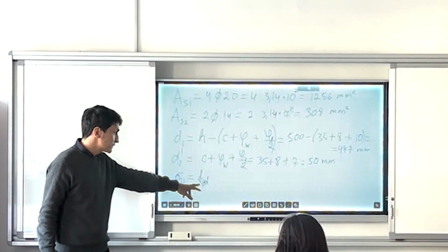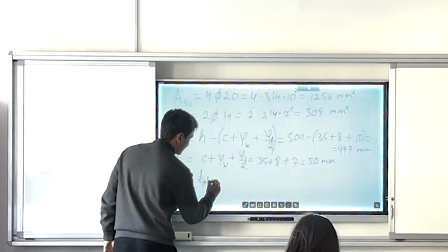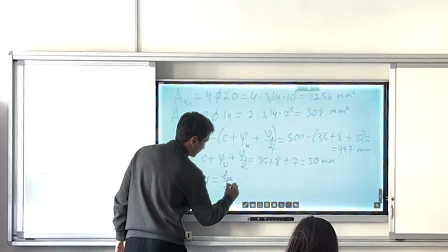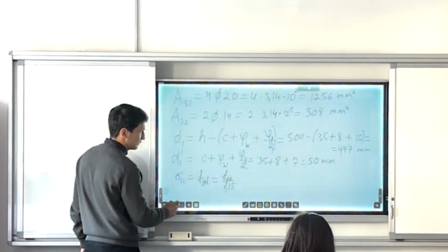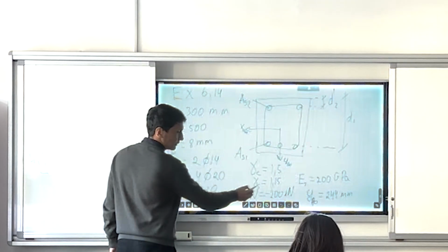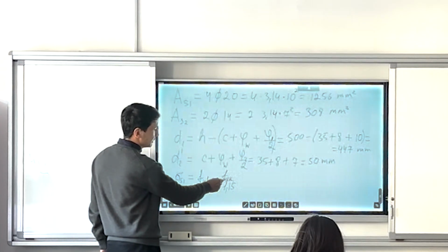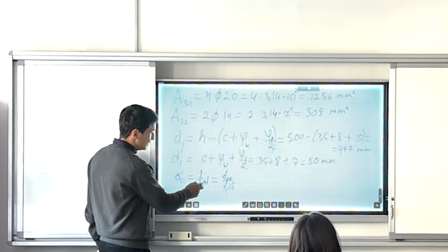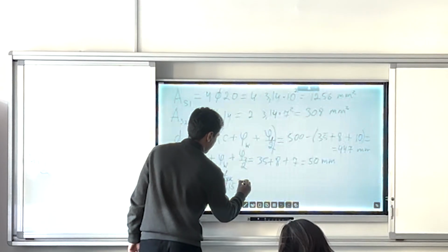So the maximum stress on the bottom reinforcement will be equal to the FYD, which is FYK divided by 1.15. So 1.15 is the safety factor for the steel, okay, for the rebars. By dividing the characteristic yielding strength of the rebar, I'm finding design yield strength of rebar, of the bottom reinforcement. So this will be equal.